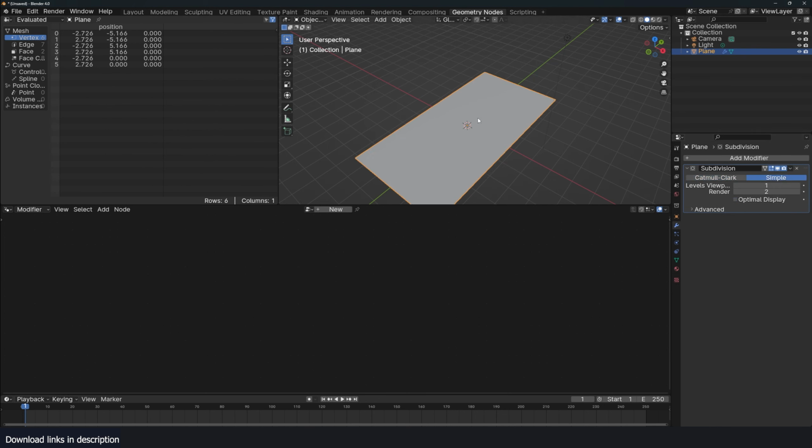Let's remove the physics or gravity and everything. So I'm going to go to field weights, remove the gravity, go to the velocity, make sure that is also set to 0. And the start should be something like 0.5. The end should also be 0.5. The life, as long as the timeline doesn't matter. So if we play back, we don't really see much, but we are not seeing the particles falling anymore or having any animation, and that's what we want.